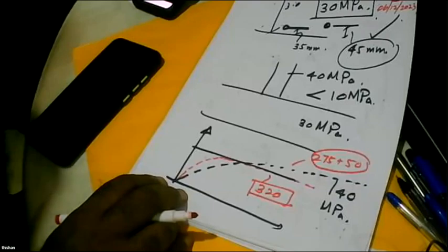By that time, you will find it's a 50-story building, 30 floors have been completed, and by the time the second year goes, all the floors are completed. By the time the maximum dead load comes on, the raft is not a 30 megapascal raft, though you designed it as 30 megapascal in 28 days.